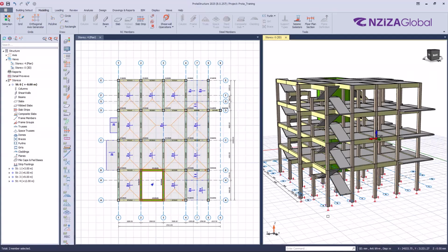However, what I can advise you, before doing a generate story command, before copy pasting, you have to make sure that there are no errors on that story, because if there is some error, then it will be duplicated to the other stories. So make sure everything is okay before doing copy paste.